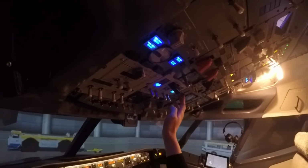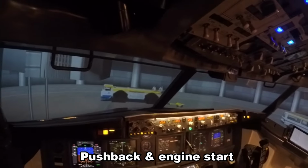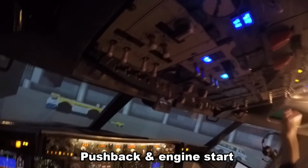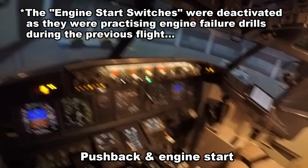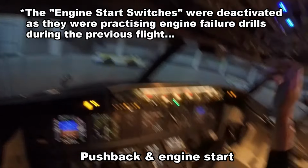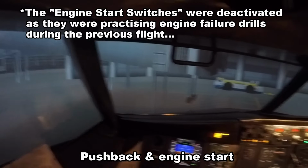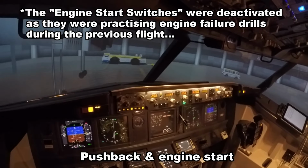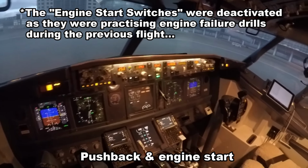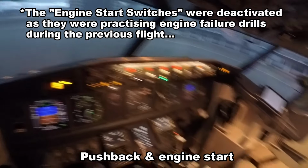We can release the brakes and start our pushback. So start sequence is 2 then 1. Let's start number 2. Cabin crew arm doors and cross check. So the N2 is approaching 18. We'll just have our engine start switches to idle.